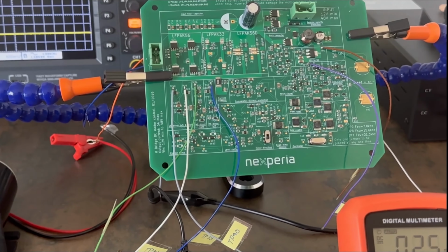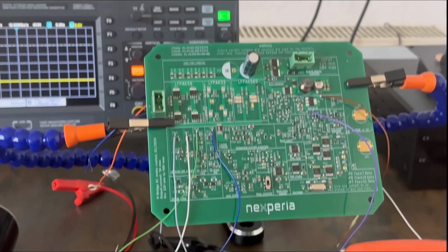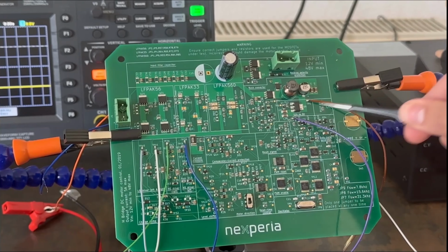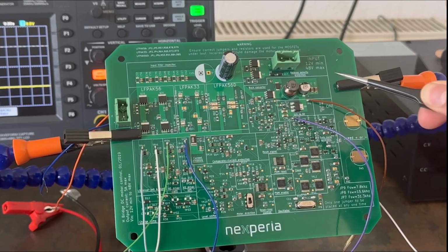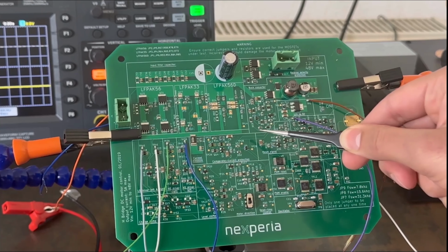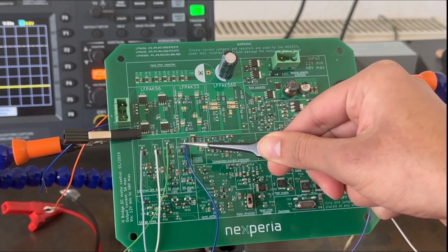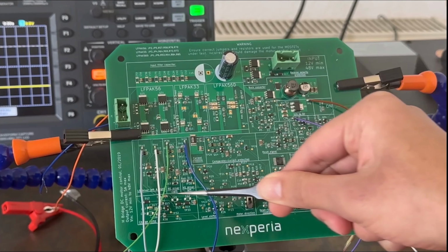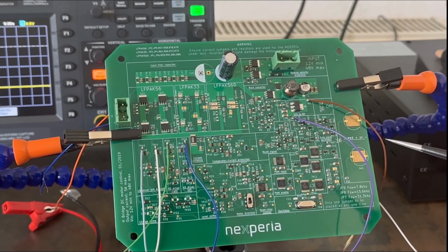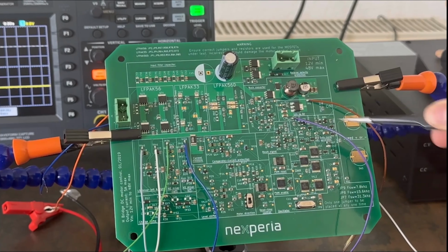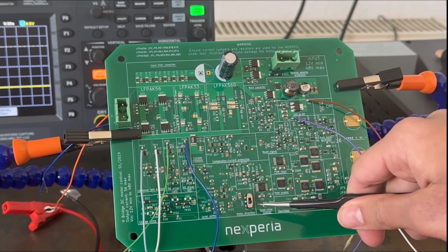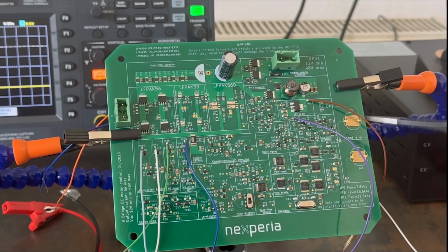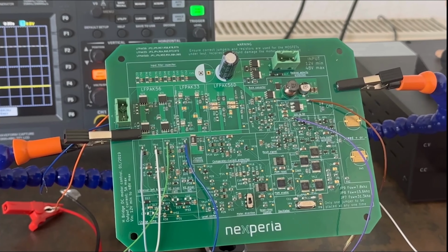Well, enough of the theory. Let's check the circuit again. This is the power supply section with buck converter. This is linear regulator, overcurrent protection circuit. This is the low side and this is the high side MOSFET driving circuitry. This part over here is the clock and PWM generator circuit. This is the motor direction control circuit, and these are the switches to control the speed of the motor.